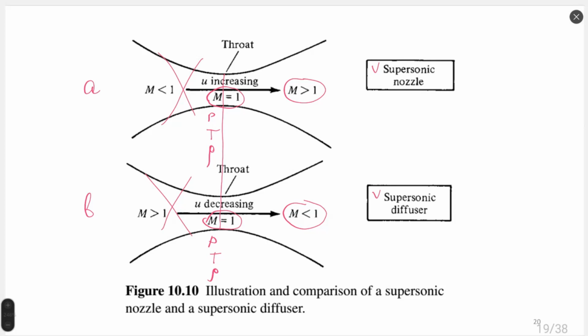Not really sure. Okay, so then I probably need to explain. Same geometries in the upper and lower picture, same flow model, same flow conditions in the throat, different results. One flow is supersonic, another is subsonic. We must understand what is the source of flow acceleration. The source of flow acceleration is always a pressure gradient. So the correct answer to my question is a pressure gradient.